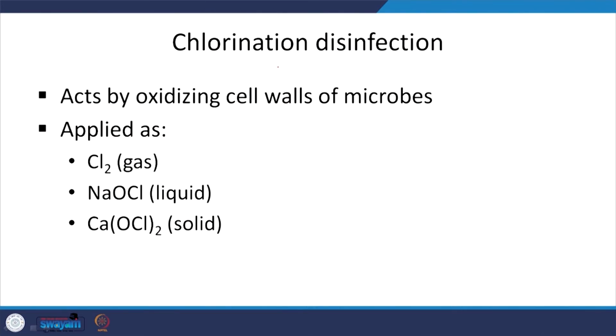Endogenous phase typically occurs later, so relatively older microbes need higher concentrations or higher contact time before they can be inactivated. These are aspects you need to be aware of, especially when looking at oxidizing agents like chlorine.